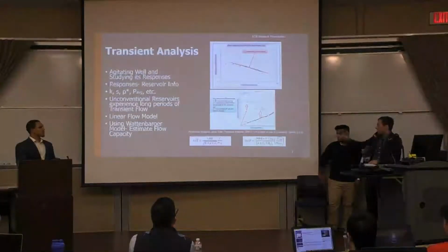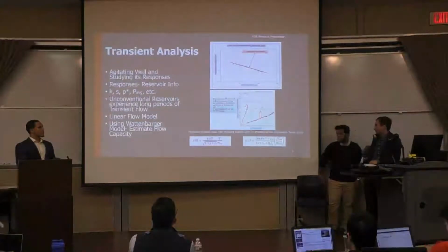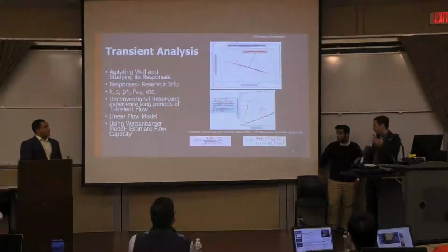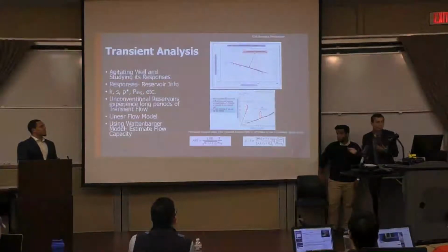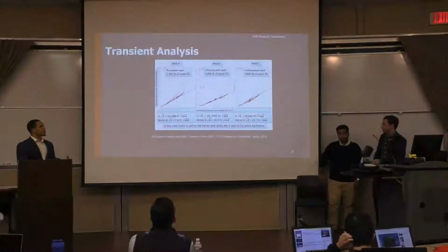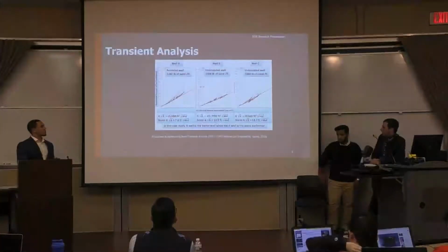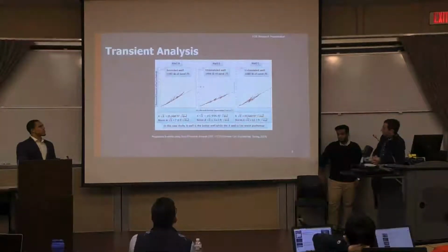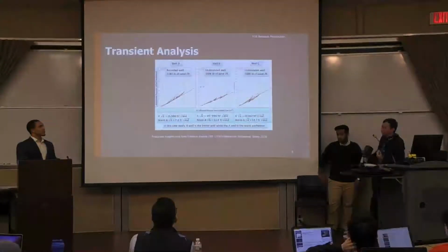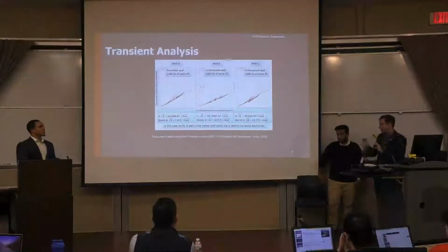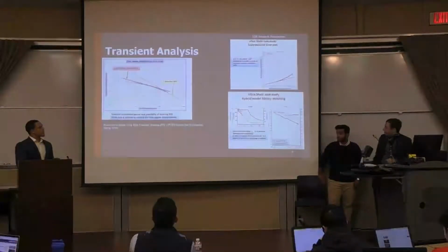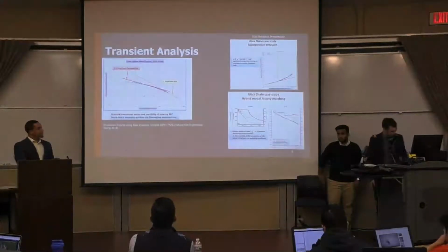And then we take our formula here and we can modify some of the parameters we find with our slope and use this original gas in place equation, which is before boundary, but it's a good comparison tool to say, okay, are we on the right track? Some other things we use this for, we can figure out our permeability and compare with completions, how it operates. So this was actually pretty revolutionary when this came out. This gave us an idea of, okay, do we need to do more sand loading? What different things can we adjust to have better performance? And obviously another case study here, you can see where they're able to history match and figure out what our production is going to be from that data.